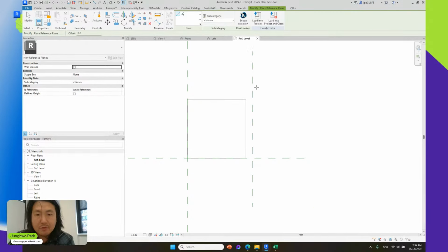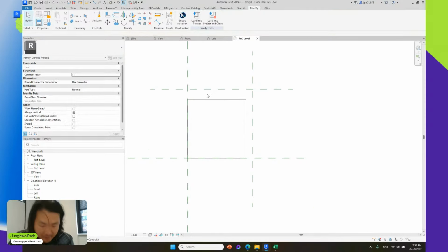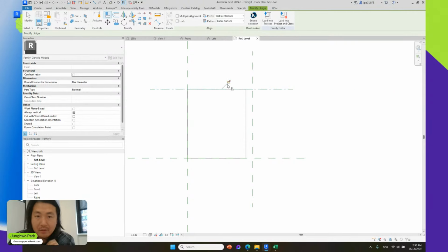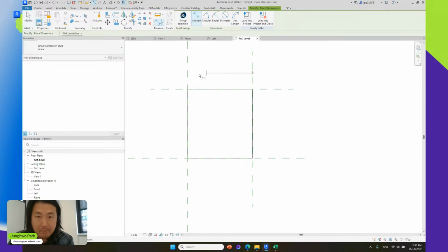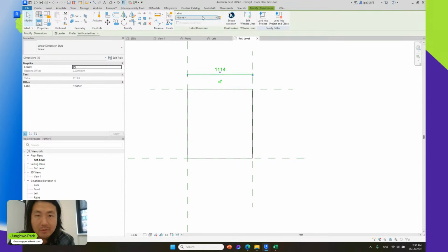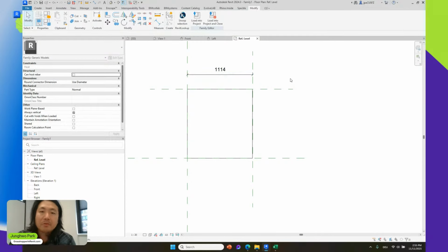If your team requires this geometry to be constrained by Revit's behavior and parameterized based on all this Revit logic, then of course building the family from scratch in the Revit family editor makes sense.